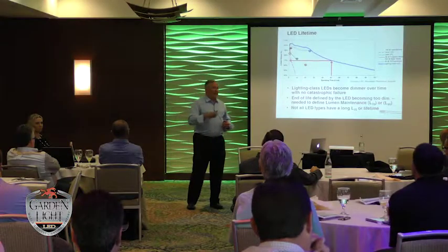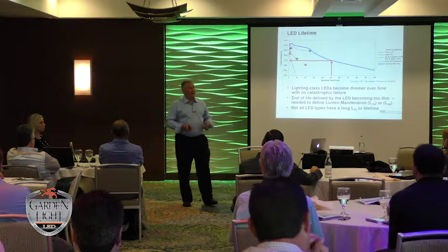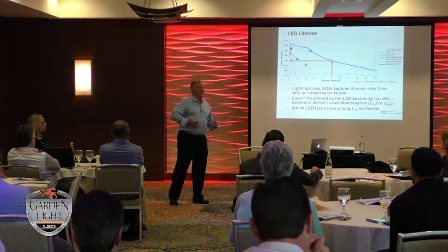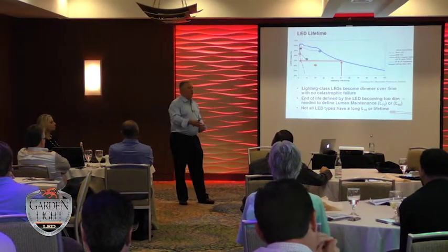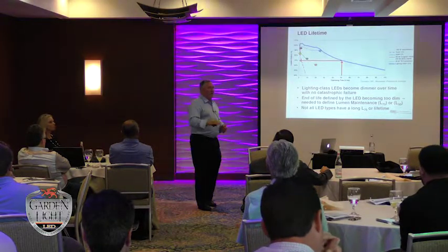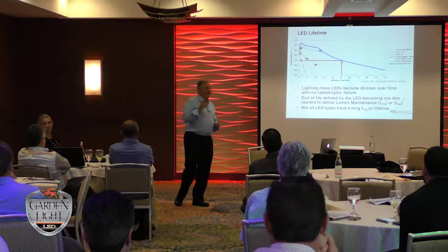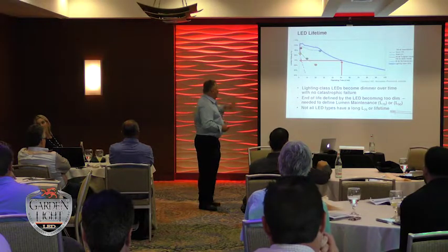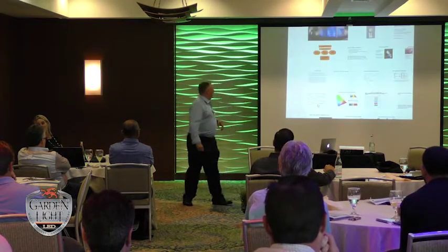I publish numbers like L90s of 190,000 hours on certain fixtures. And the reason is the heat sinks are so good that they keep the temperature of the LED so low that it doesn't burn out rapidly. It burns out over a long period of time. Drivers, on the other hand, fail fast. That's never going to be a fixture life. That is an LED life. Now, what I say that for is I had to give a class at the IES one year, and it was about how do you judge one fixture against another.